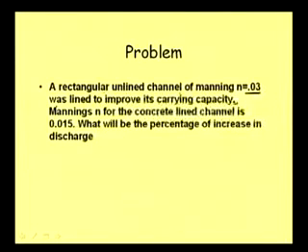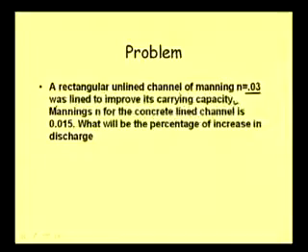This is a very common practice that is adopted in many places. I mean, like for a city also. Say we are having a drain which is, suppose, unlined, and we find that in the rainy period or in the monsoon, this drain cannot carry the amount of water that is coming to it, and that's why the depth is increasing and it is getting overflooded, and that's why flood is happening. The water that is coming to the channel cannot move out quickly, and it is creating a water stagnation problem. So many a time we go for channel improvement.